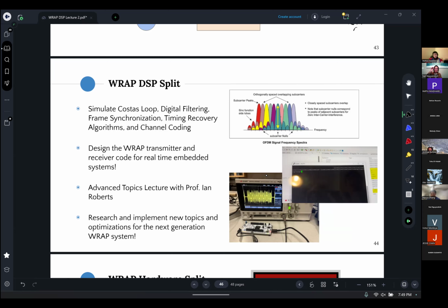That's just like how we can look at the I and Q components that we demodulate and then determine, oh okay, this is a sample, because from the microcontroller's perspective, it's just a bunch of numbers that came in. This is determining how we extract the bits from that. And then frame synchronization is how we know what bits correspond to the start and end of a message. And then I'll combine that with channel coding, which is when we can send certain messages that correspond to different bits,